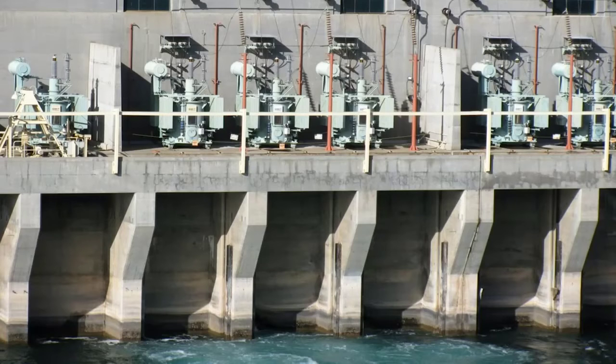There may be exceptions in using a large standardized arc flash boundary. This is one of them. If you have a situation where trying to keep people 10 feet away is going to block pedestrian traffic, especially here. But overall, it's a strategy that some have been using. And as I said, it does greatly simplify the labeling and the need for relabeling. And so at the end of the day, the label is to advise you of what the hazards are and how to protect yourself from the hazards.